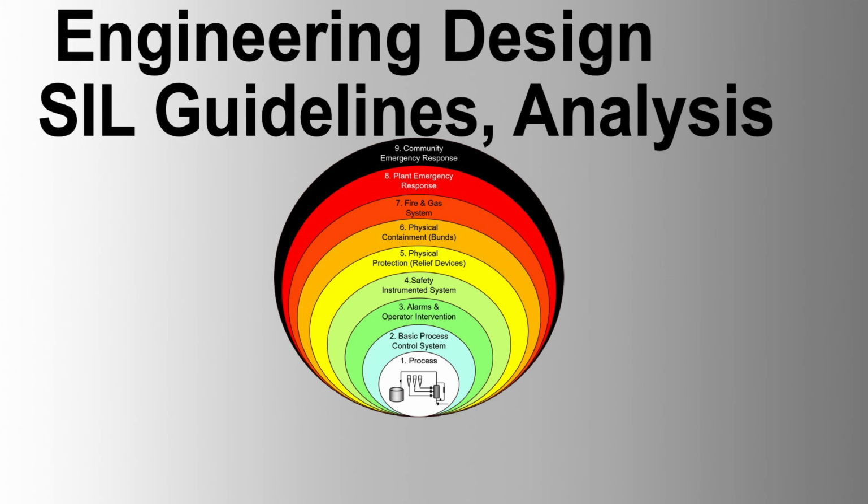1. Assign safety functions. Each safety function is assigned to its SIS as defined in the safety requirements specification. 2. List components. List all components that have a safety impact on each safety function, including logic solvers, sensors, and final control elements. 3. Identify failure modes. List the possible failure modes for each component. 4. Determine system states. Identify degraded, intermediate, and failure system states by systematically introducing different failure modes of each component and their effect on the safety function. Construct the Markov model by determining how the SIS can be repaired from these states.